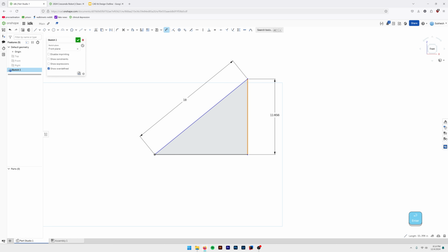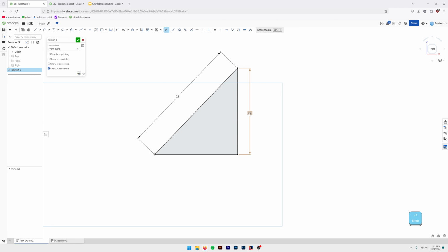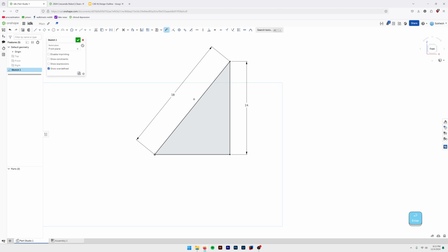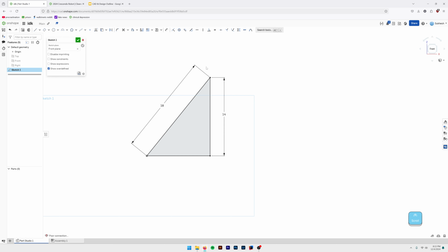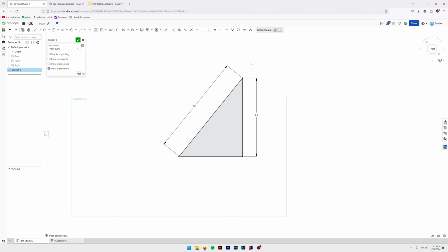I'm going to do it again. D over here. Left click again. Type whatever inches you want and then press enter, and that creates a dimension. Notice how the shape was blue-ish with this black over here, and then when I dimension this, everything turned black. That means your shape is fully defined and fully constrained. This is good. That means I cannot drag this shape because it has all its relationships defined.